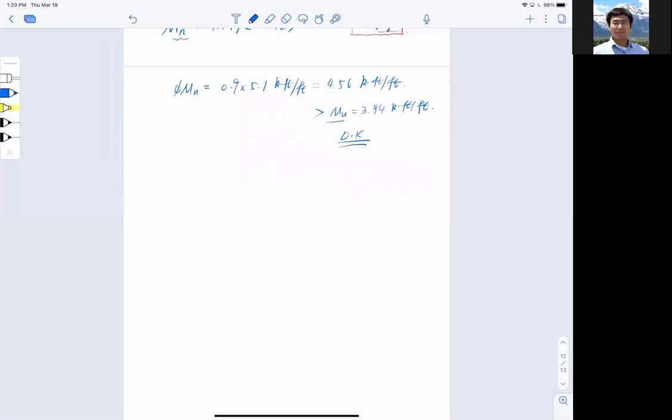So with this now, we can say I have my reinforcement detailed. Looking back, I just want to draw the section to tell everybody this is my design. This is per unit strip, and forgive my poor writing here. So 12-inch, and I have a bar right here, and the depth of it equal to 4 inches. The height of it equal to 5-inch, and I have a number 4 bar. So that is my section per unit strip. I'm pretty stoked about it. I have my final section design.